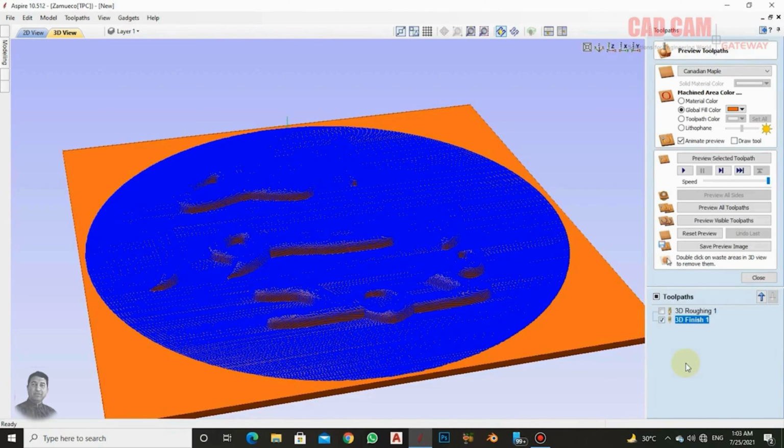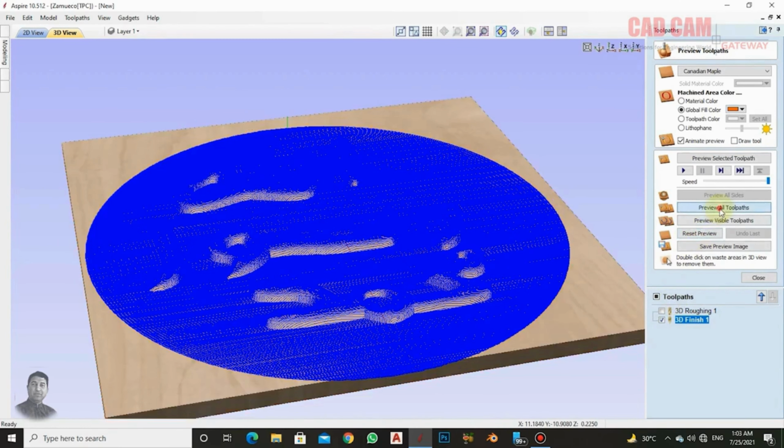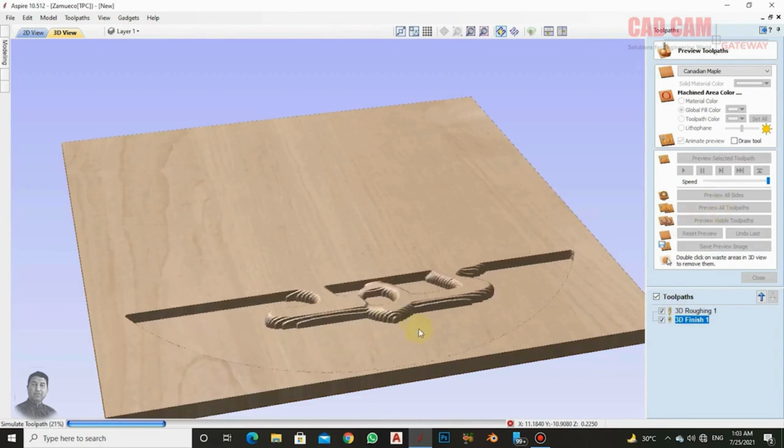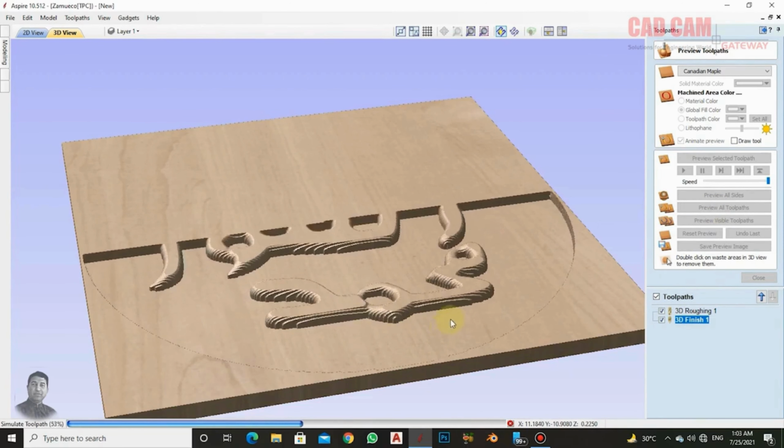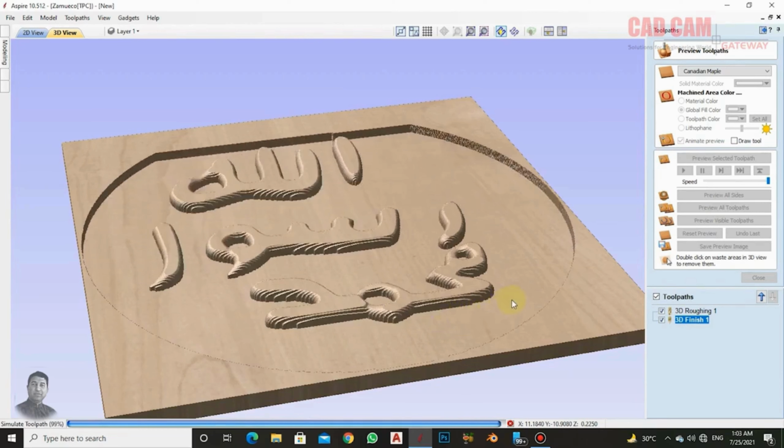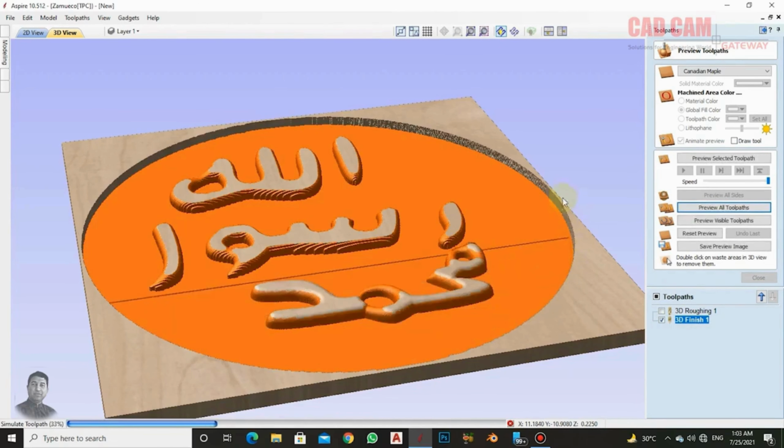Once tool calculation is complete, check the preview. Then we'll add the round. Two ways to apply this round. One, make a complete circle and cut the round. The other, use the natural axis shown or selected. You can cut it that way too.